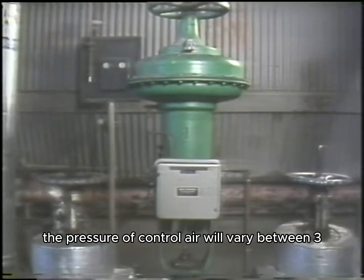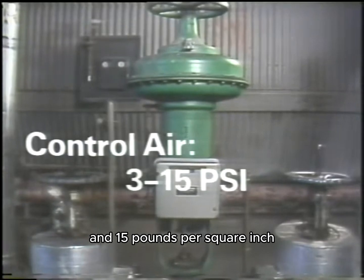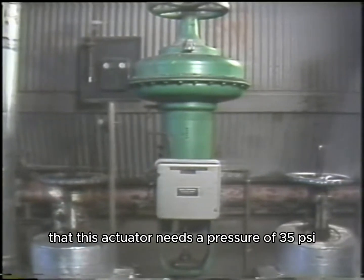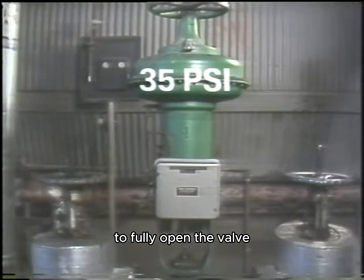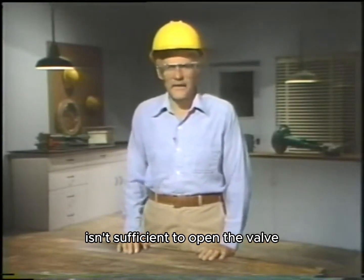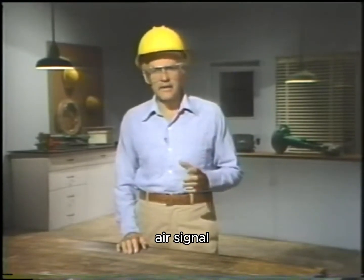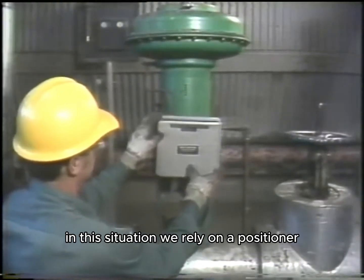Typically, the pressure of control air will vary between 3 and 15 pounds per square inch. However, the manufacturer states that this actuator needs a pressure of 35 psi to fully open the valve. Obviously, control air pressure alone isn't sufficient to open the valve. To operate the actuator and its valve, we need a way to multiply the force of the control air signal. In this situation, we rely on a positioner.